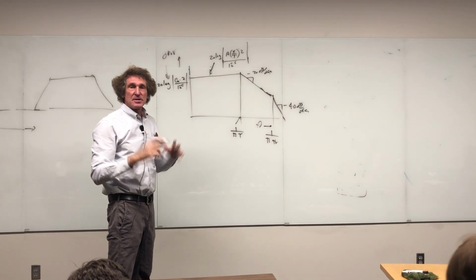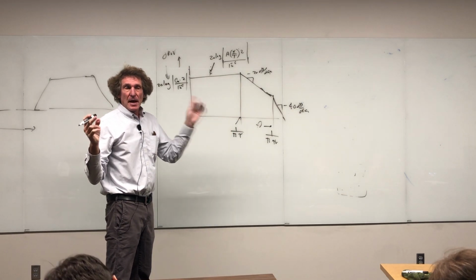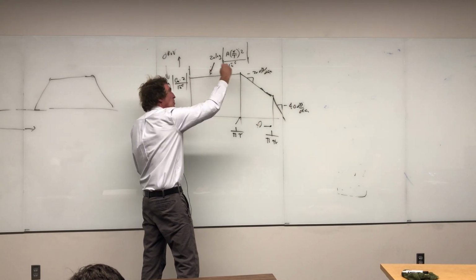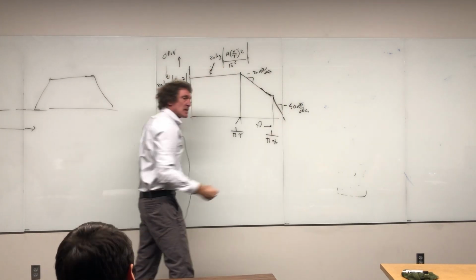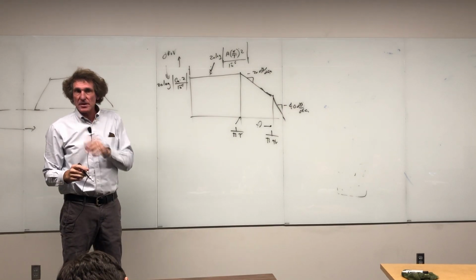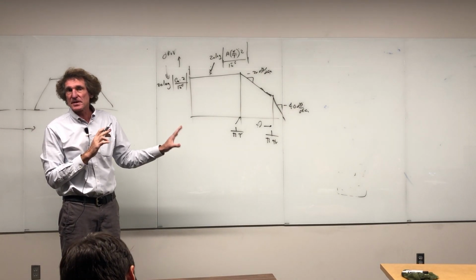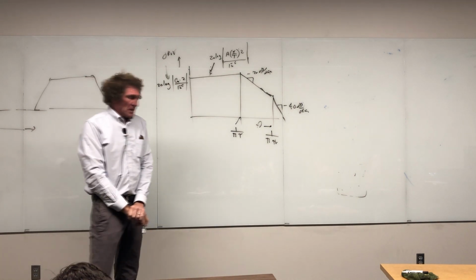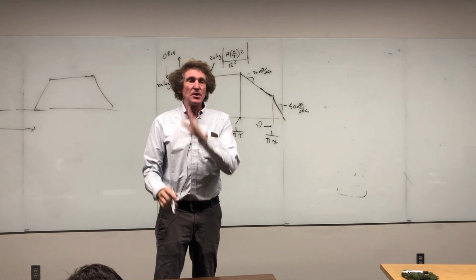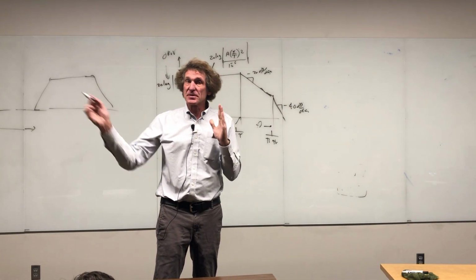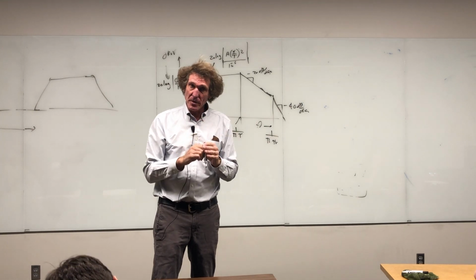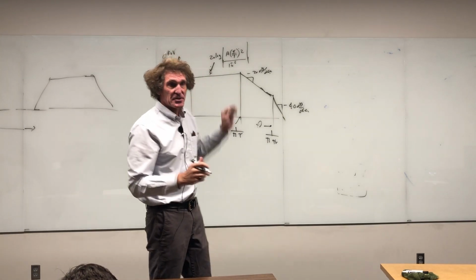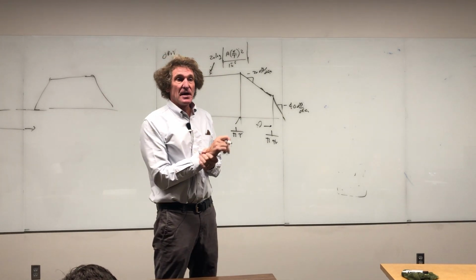Last time I actually did the proof on this one. And really what's happening here, to be frank about it, is this is an envelope. There's a whole lot of oscillations, but when we do EMC analysis, we look at the possible worst case effects always. So that's why you don't have the cosine of... We absolutely know they'll be at distinct frequencies. But the thing is, this is the envelope that you worry about when you do EMC analysis. You're always looking for worst case effects. This is the worst possible signal, or spectrum of the signal that comes off of that. And that's the way you do it.